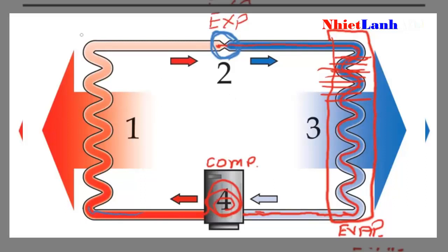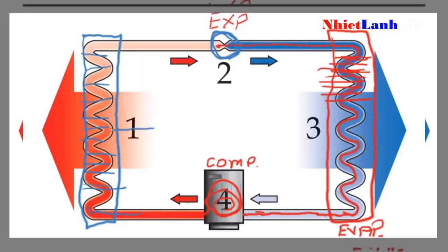And the condenser coil is similar to the evaporator coil in that its job is to dissipate the heat. So it's also got lots of aluminum fins attached to it to help expand the surface area, and the air blows over this coil and blows the heat out of it. So as this high pressure, high temperature gas travels through this condenser, the gas condenses into a liquid, and that's where the condenser coil gets its name as a condenser.